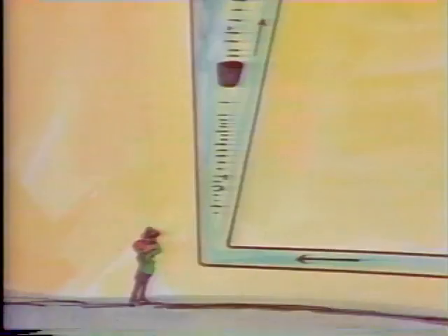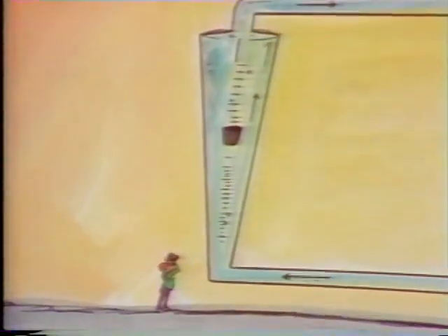Volumetric measuring instruments like positive displacement flow meters and rotometers are very accurate ways of measuring flow rates. However, they do have some limitations. One of the limitations is size, since these meters must be sized to accommodate the volume of fluid flowing through them. They're not practical for measuring extremely high rates of flow. The meter itself would have to be too large to be practical. For situations like these, it's necessary to measure flow by another means.